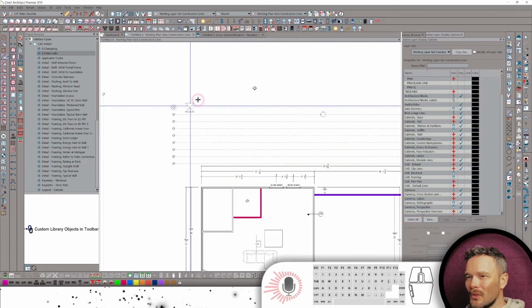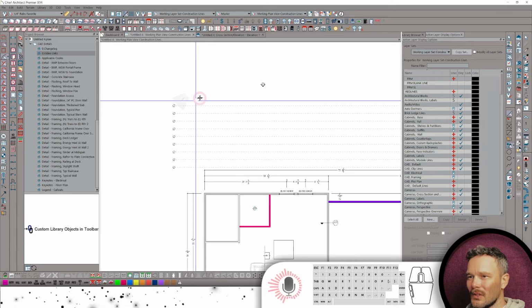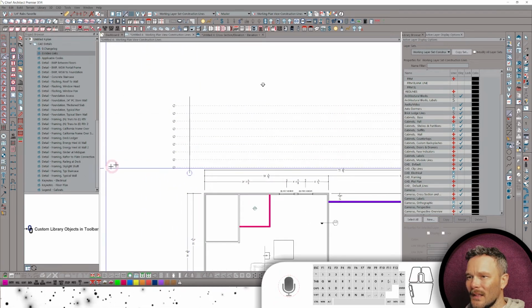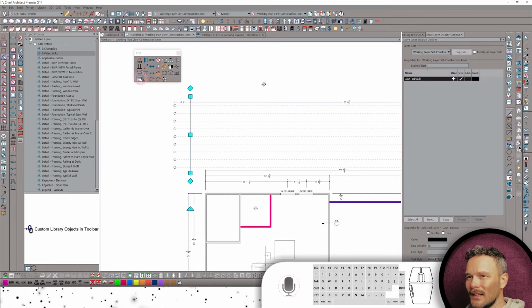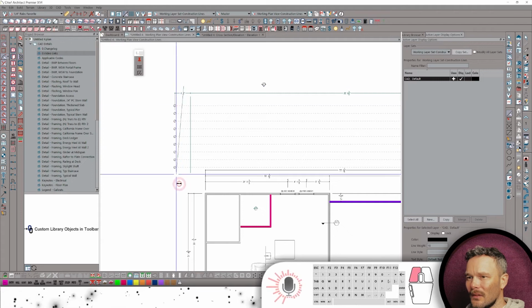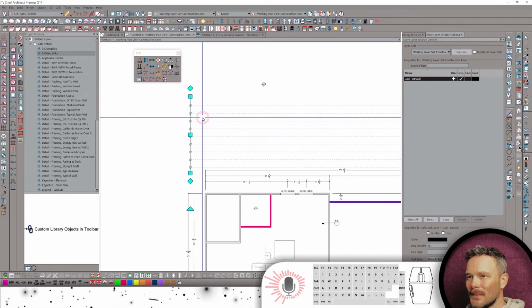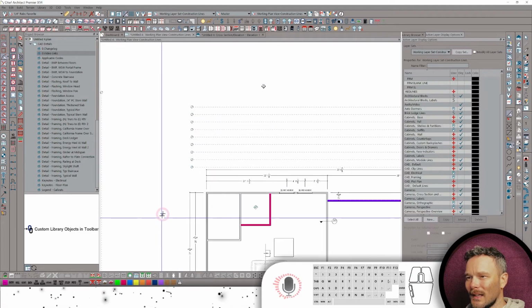Of course, the trim tool works as well, so we can always just draw a line. We've got our construction lines too long, right? Then select that line, use that trim, and then draw a line through those construction lines. They're going to snap to that line, and then you can delete that as well.